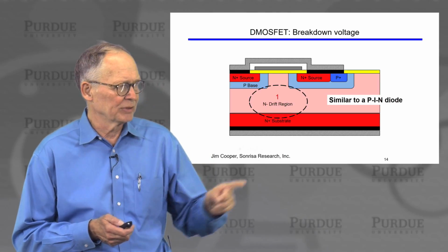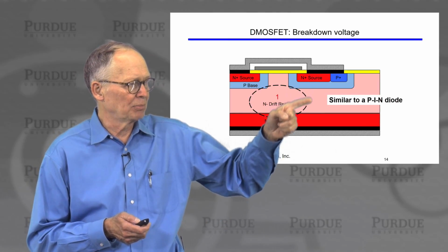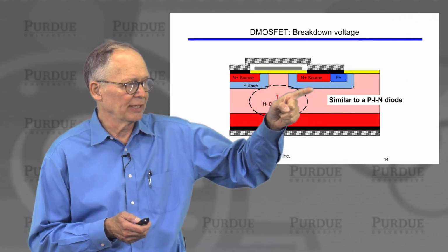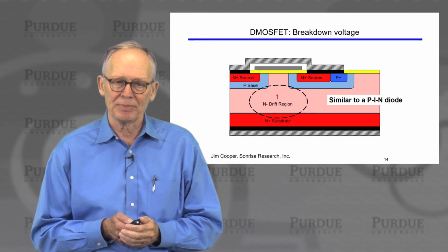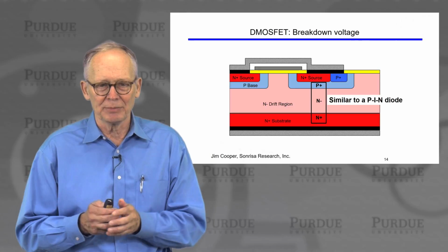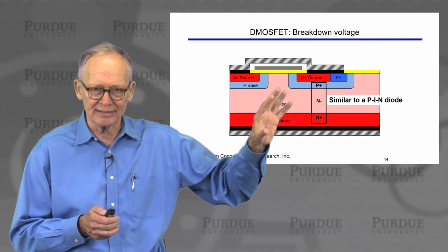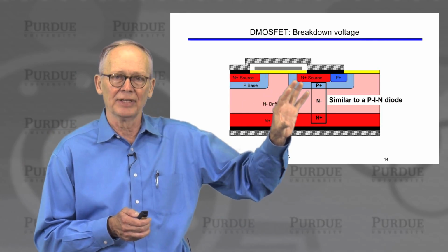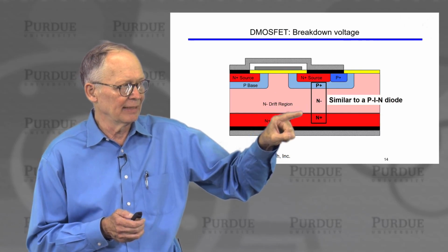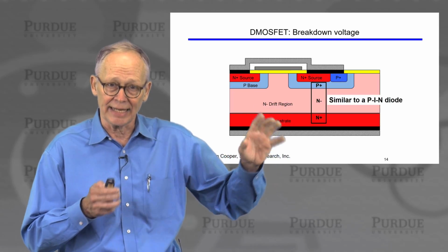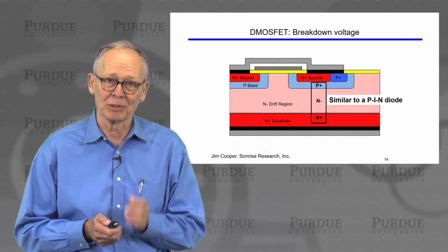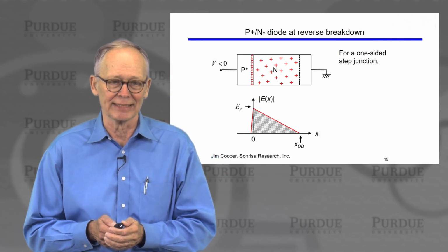Now, if I look at breakdown voltage, you can see here that I'm going to be applying a large voltage to the drain. I have an N lightly doped layer P structure. This is like an NIP diode. So in reality, there are 2- and 3-dimensional current flows, but I can get the gist of things by thinking of the breakdown event as occurring as the breakdown voltage of a P plus N minus lightly doped N plus PIN diode. That's a much simpler one-dimensional problem to analyze, and we can make some headway by doing that.